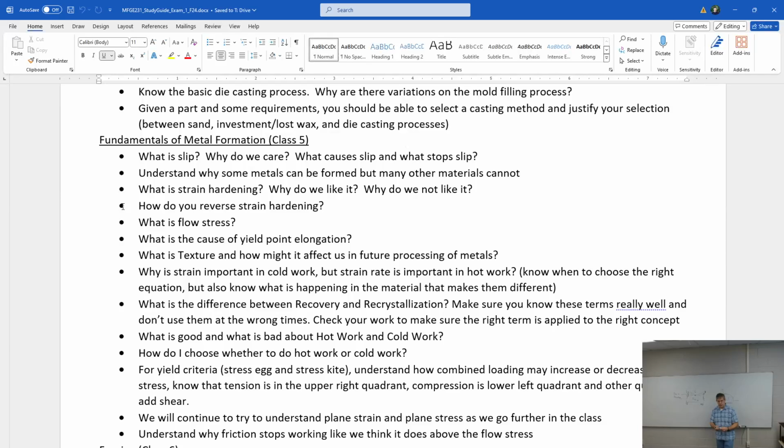Also, hot rolling has the same problem as all hot work, that it's quickly reacting with the environment. The grain is growing really quickly, so the material's becoming weaker. It's not going to create square edges because the part's gonna shrink afterwards and change shape.